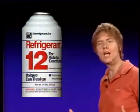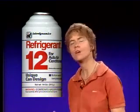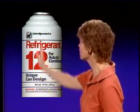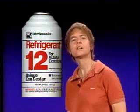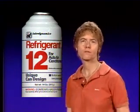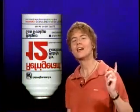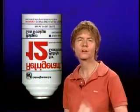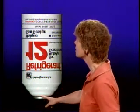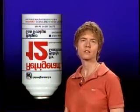Now, when you are adding Freon to the system, normally you're going to be adding Freon vapor, and you would want the can to be vertical with the outlet up at the top. But suppose instead that you want to add liquid Freon to the system. You've got to do it differently. When you're adding liquid Freon to the system, you place the bottle vertical still, but this time the outlet has to be down at the bottom in order to put liquid into the system.